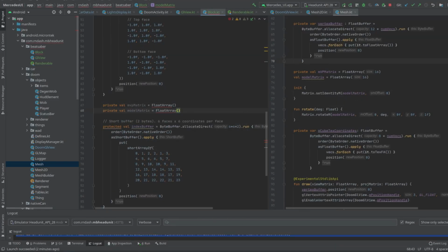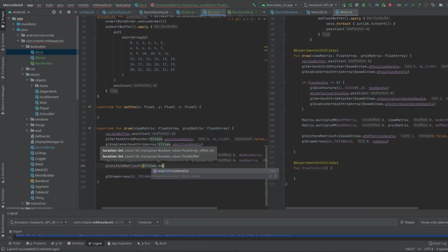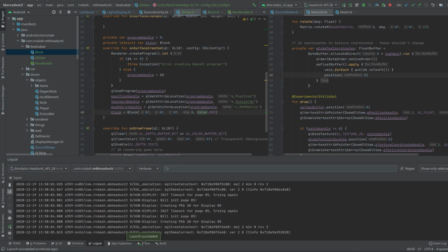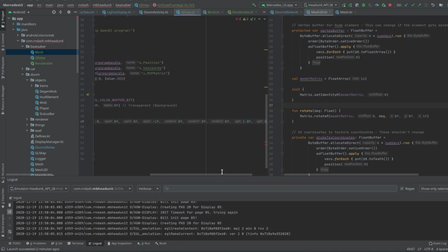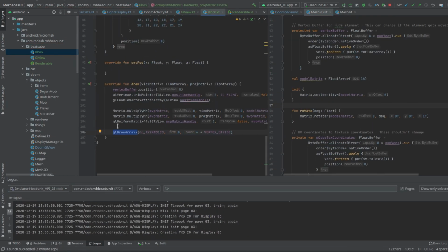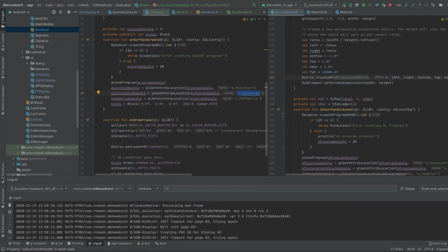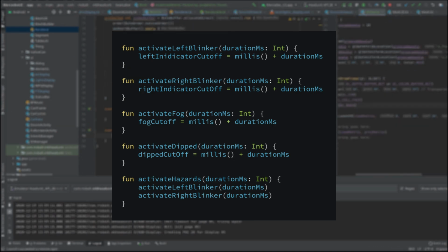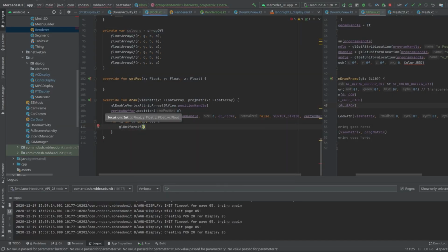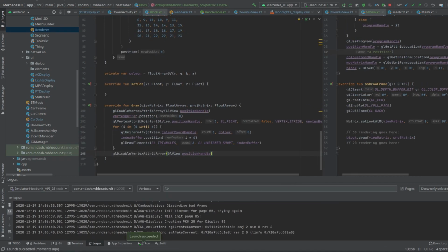The blocks will be heading towards the camera at a certain speed which is calculated based on the beats per minute of the music, which is provided by the map data. Utilising the party mode class I created in part 2 of this series, sending commands to the lights is really simple. I simply have to call functions to activate or deactivate any of the lights, and the background thread will deal with sending the CAN frames to the car's network in order to achieve the desired results.